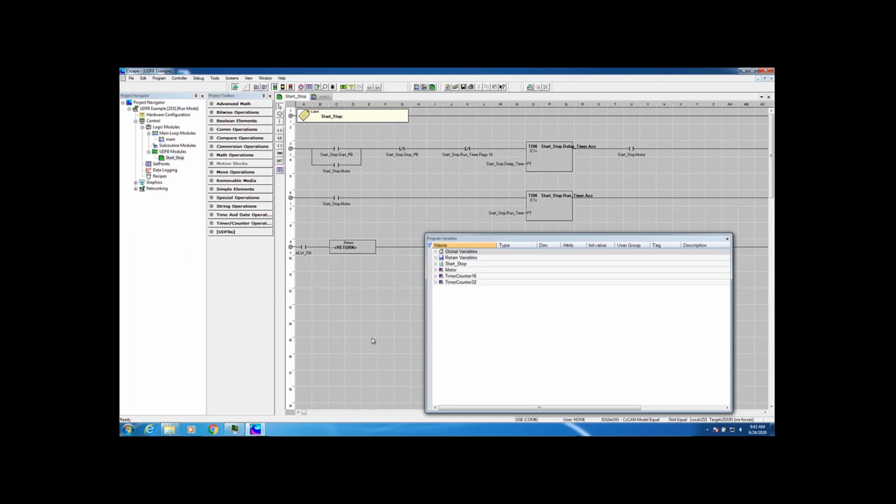One of the most powerful features in tag-based programming are user-defined function blocks. A user-defined function block is a powerful way to reuse sections of code. They differentiate themselves from subroutines as you can have multiple instances of user-defined function blocks, all running simultaneously with their own dedicated sets of variables. So if you look over at the project navigator in the top left, you'll see the normal main loop modules, subroutine modules, and below that you have the UDFB modules, which is unique to tag-based programming and IEC package programming.